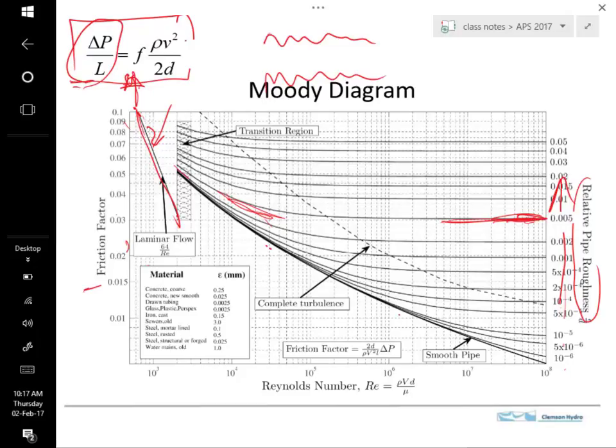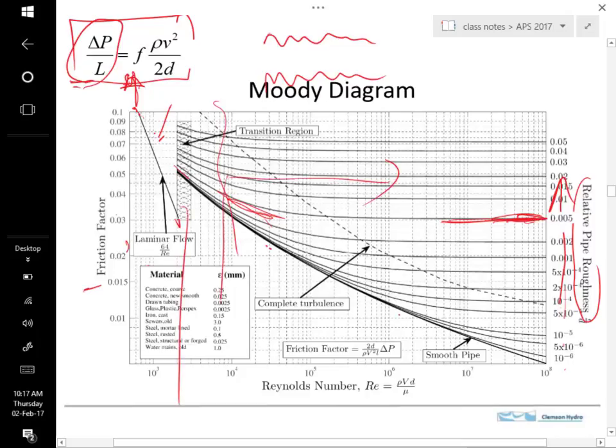Okay, so this is doing the same thing that we saw conceptually, but with more variables, with the pipe roughness, for example, included. We also see this kind of peculiar transition. This is under laminar conditions, and this is under turbulence out here, but right in here, strictly speaking, just right in this range, is the transition from laminar to turbulence, and there's this jump in the curve. And this is established from these laboratory tests.